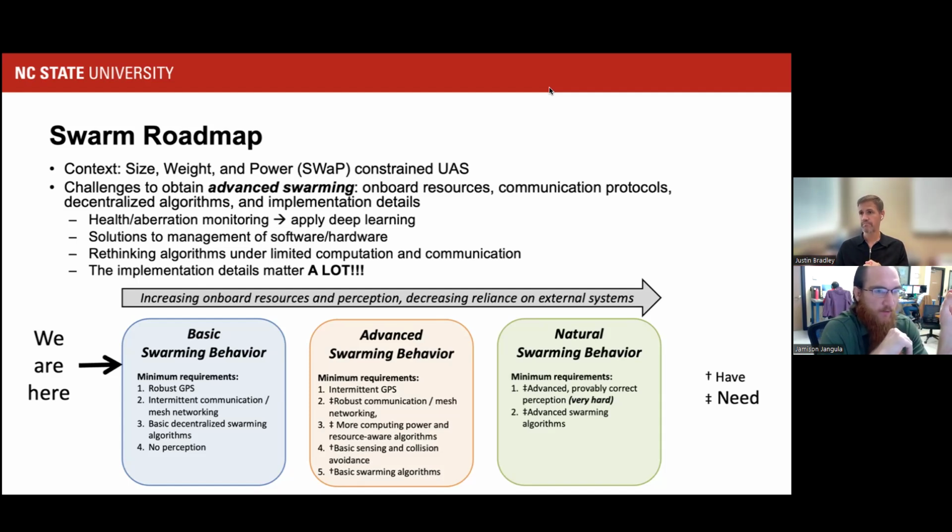How much, if you just have the Raspberry Pi and RF module, how much does that decrease it? Oh, that's a good question. You mean from a payload perspective, right? Its burden on energy is pretty minuscule. The vast majority of the energy consumption is taken up by motors. We build custom containers for our radio and computer out of lightweight carbon infused 3D printed plastic, so they're pretty lightweight. That only bites into the flight time like a minute or two. So it's not very significant.